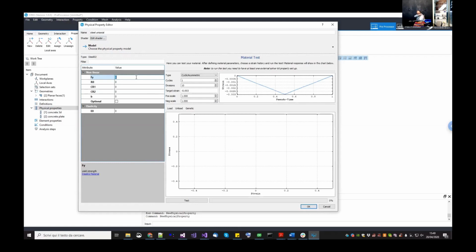Okay, for some reason I didn't print it, but anyway, I choose a value, then you can see from the real one. Oh no, I have it here. Yes, it is 476. Then these parameters that define, if you remember, the hysteretic loop, I've chosen 30, 0.925, 0.15, and then I calibrated this B parameter, which is the strain hardening, to a value of 0.015, because in this experimental test,